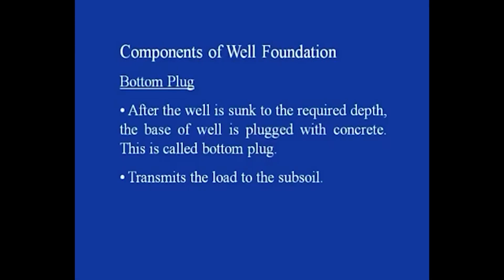The next component is called the bottom plug. You know beforehand at what depth the well is to be sunk. So once the well has reached the required depth, the base of the well is plugged with concrete, and that plug is called the bottom plug. The function of this bottom plug is that it transmits the load to the subsoil.